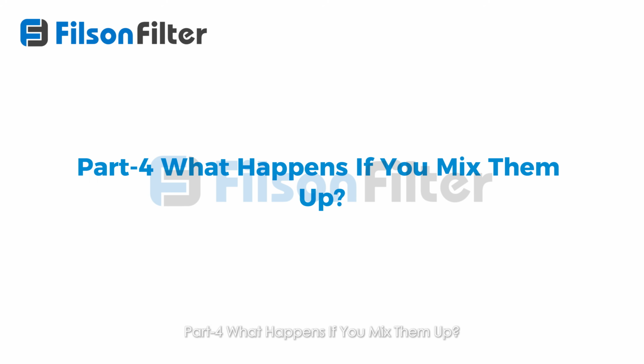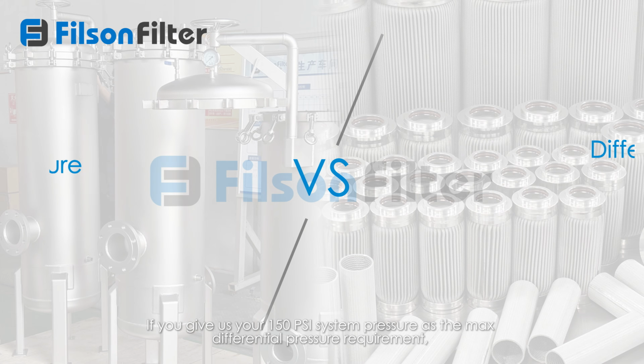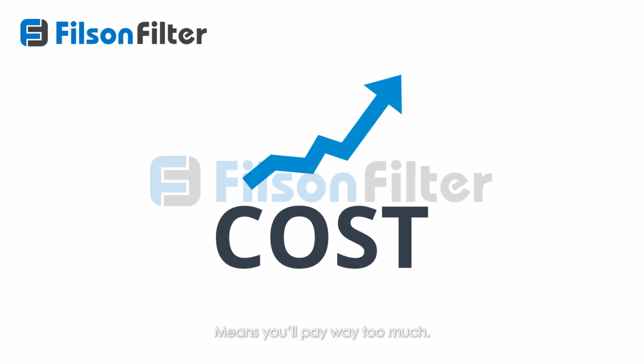Part 4. What happens if you mix them up? And why mixing them up will hurt your project. Let's look at an example. If you give us your 150 psi system pressure as the max differential pressure requirement, your filter element will be heavily over-engineered. Means you'll pay way too much.